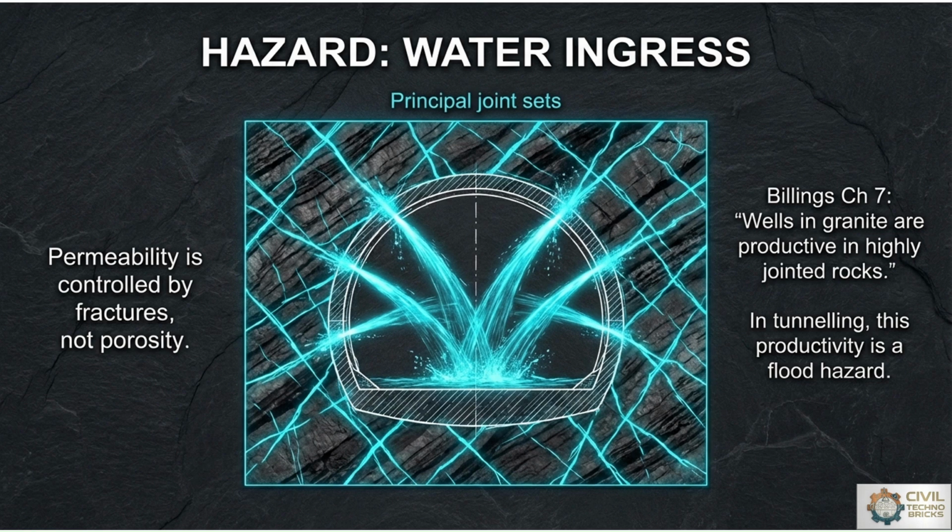Weak geological formations increase the possibility of deformation and instability. Seismic activity and fault zones may create additional structural risk. So geological defects such as joints, faults, folds, and shear zones influence tunnel stability. Jointed rock masses may create wedge failures during excavation.